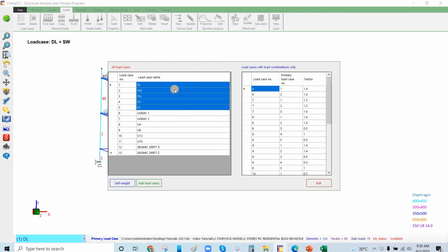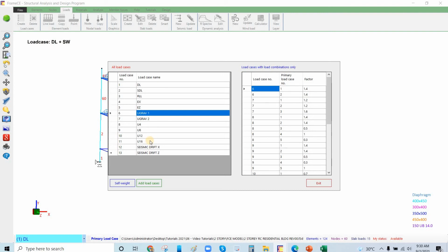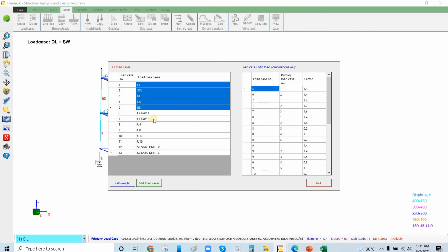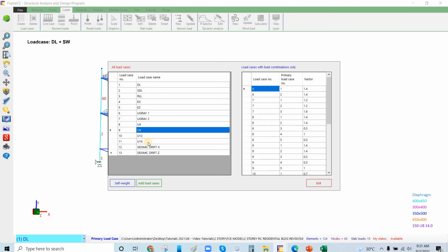So in this, the wind definition, or how to define the wind, is already uploaded, and in this case I deleted it. I can also define it again, but for now I will just consider these load cases, gravity and earthquake. This model doesn't have a wind, but we can define it again. In this case I will just show how to review the wind load. We already uploaded how to do the wind load case and the load combination.